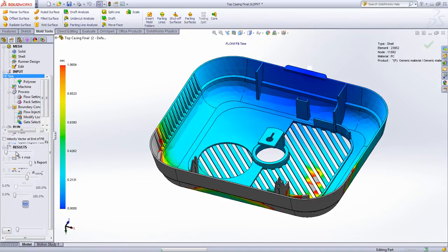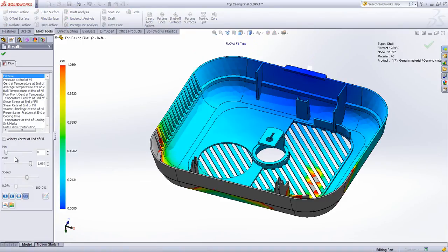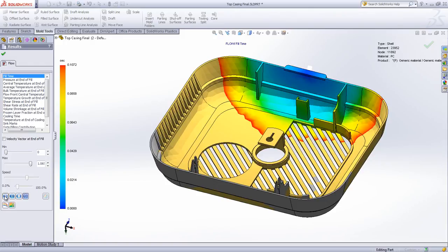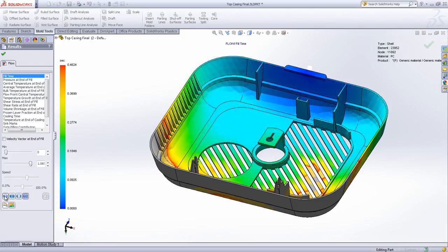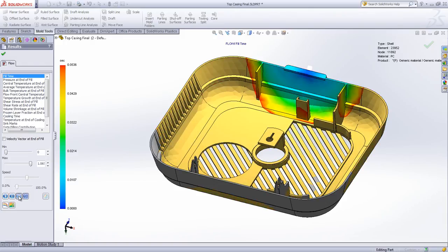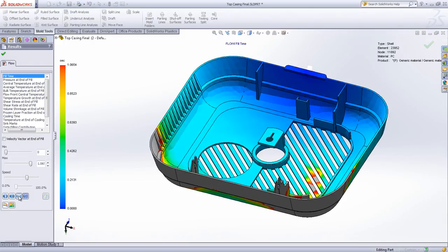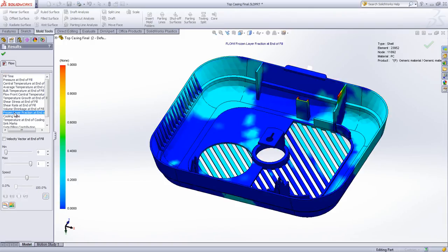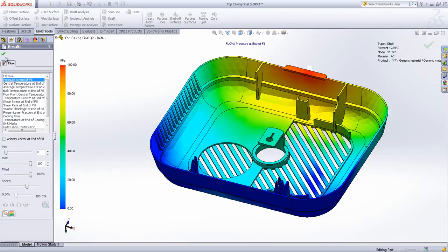With the same injection location and material, you can see that we ended up with another problem. Because we decreased the thickness too much, we created a short-shot problem. No matter what you do, how you set up the machine, or how fast you inject the plastic, you just can't get the plastic to fill up 100% of the mold cavity. This moldy part would be nothing but defects.